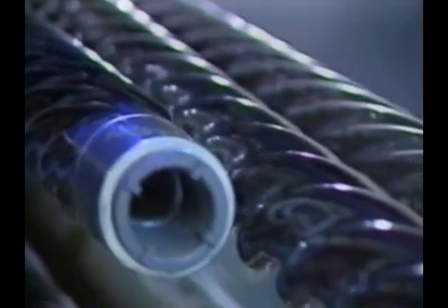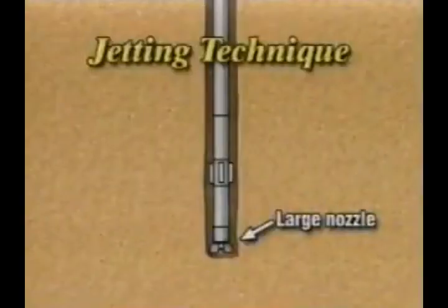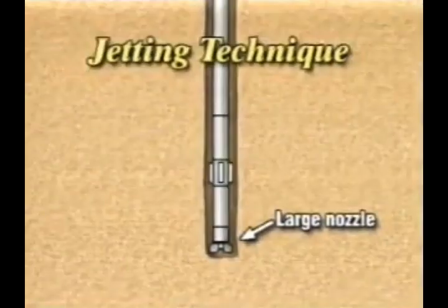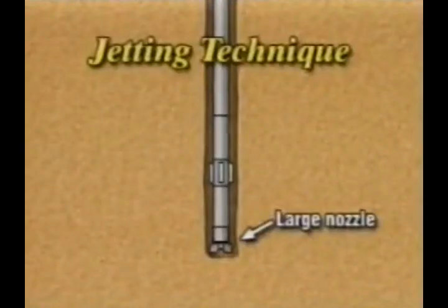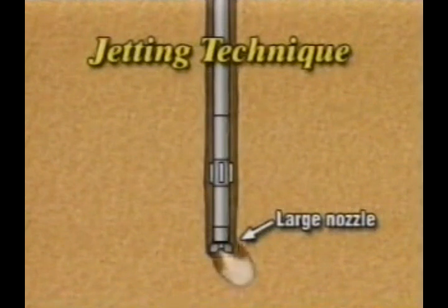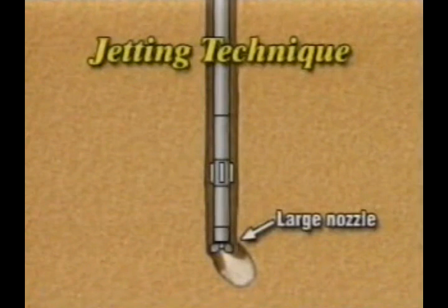Although the mud motor is overwhelmingly the tool of choice for controlled directional drilling, there are other ways of initiating deflection that may be applicable in certain areas. In very soft formations, for example, jetting bits can prove effective. These bits have orienting nozzles which use hydraulic energy to gouge out a small pocket in the formation, after which the driller can drill a small pilot hole, run a directional survey, and reorient the bit if needed.